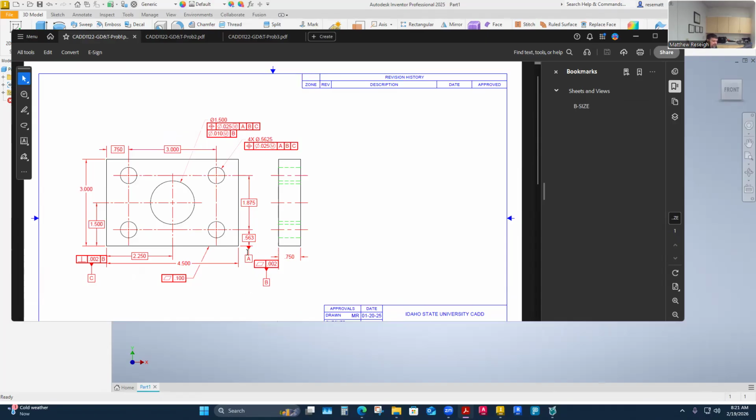So I'm going to do a couple things. I'm definitely going to move datum A to make sure that it clearly shows that it's a surface datum, like the front side is sitting on that bottom surface. Datum B, I'm going to clearly show that it's the same surface, but I want it to be the actual front surface right here. And datum C, I want to be this left side surface. And so I'm going to make that a little clearer.